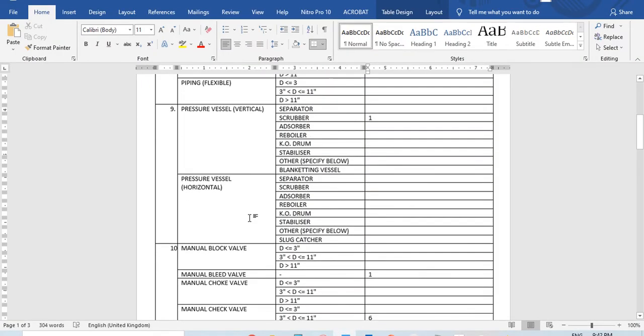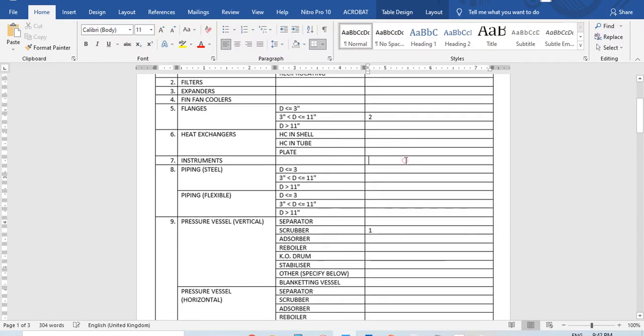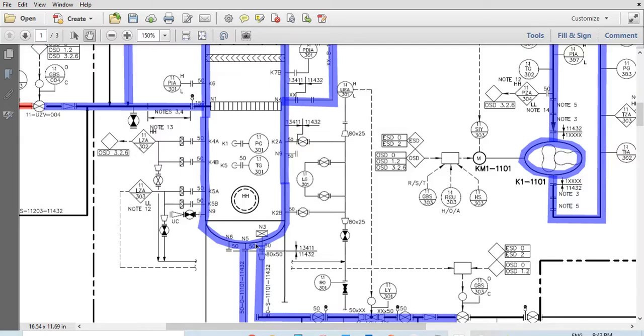Now the reason why we're doing all this is because we're going to use all these numbers with the failure frequencies. We're going to multiply them with their failure frequencies. There's a document called OGP, or Oil and Gas Producers, and there's historical data of all the pipes that have failed and the hole sizes and that kind of stuff, ignition probabilities. So we're going to multiply these numbers by those failure frequencies. So we need to get all the numbers from here.